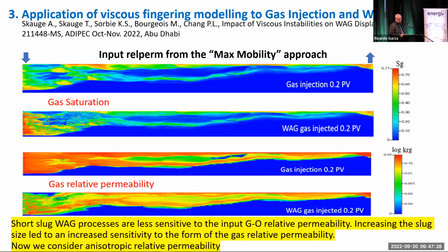And that is compared to the WAG scenario. In the WAG scenario, we started out with gas, followed it with water. So 1/10 of a pore volume with the gas first, 1/10 of a pore volume with the water, and then I'm changing back to gas. And after the second gas cycle, then I see these results.